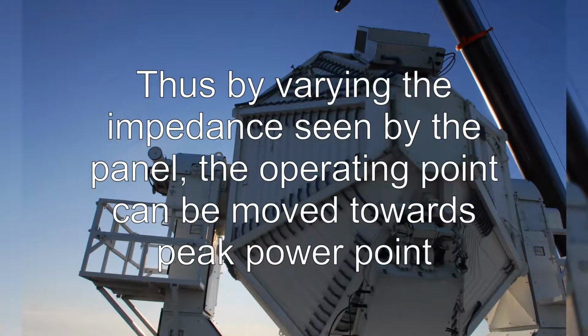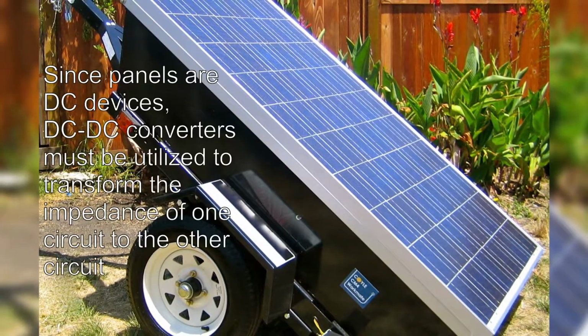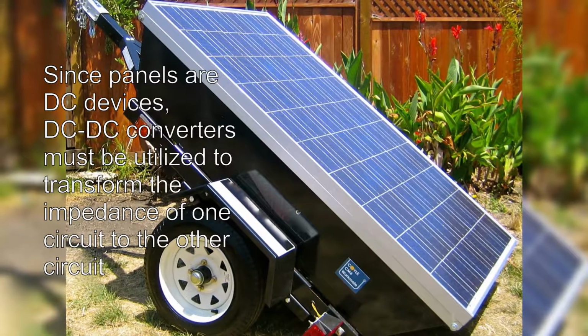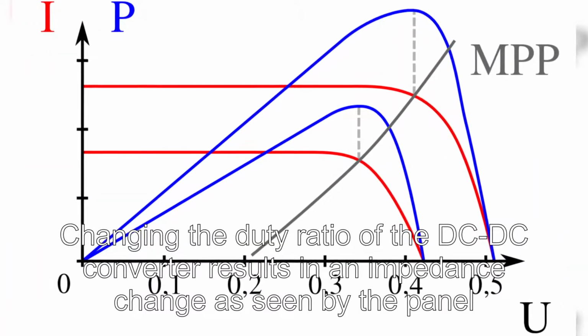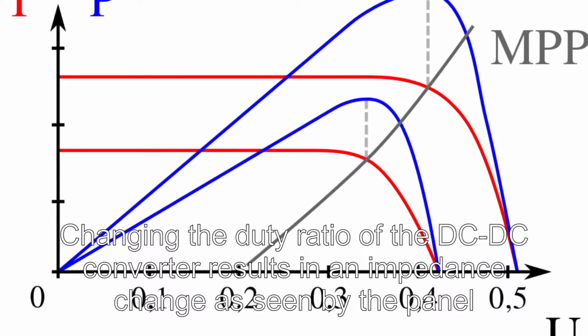If a full power voltage curve is available, then the maximum power point can be obtained using a bisection method. When a load is directly connected to the solar panel, the operating point of the panel will rarely be at peak power. The impedance seen by the panel determines the operating point of the solar panel. Thus, by varying the impedance seen by the panel, the operating point can be moved towards peak power.